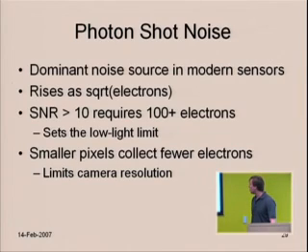What's left is to get more electrons, and you're either going to need more glass out front with bigger holes in it to get the light through, or you're going to need a higher efficiency sensor. Sensor quantum efficiencies are already in the 40% range, so there's a factor of 2.5 to get there, and then you're done.